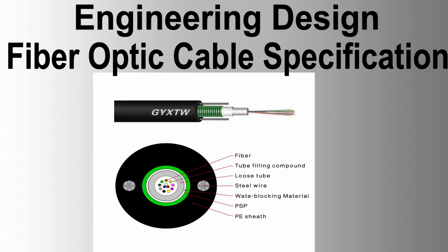Bend radius compliance. The bend radius of HDPE cable conduits when entering and exiting each manhole will comply with the specification requirements. HDPE conduit bends shall not be made within 2,000 millimeters on either side of a conduit splice.